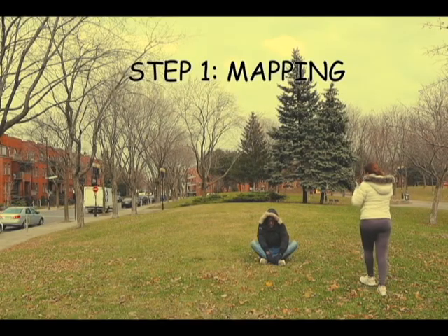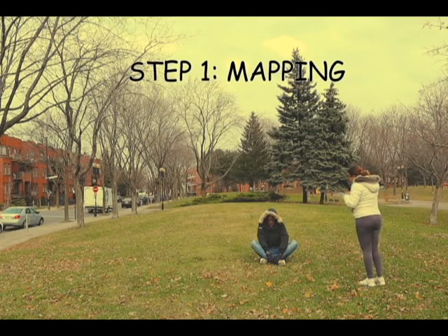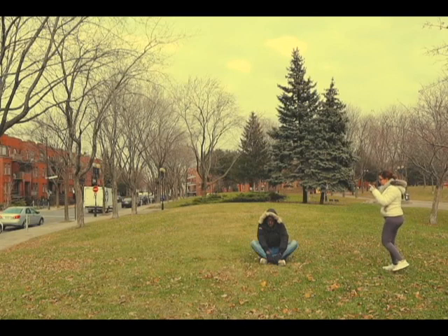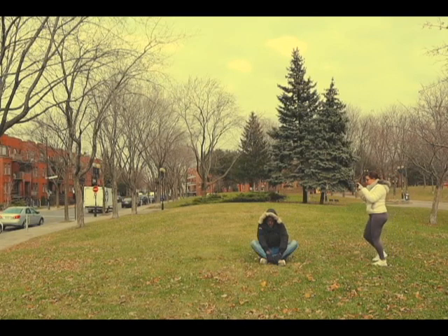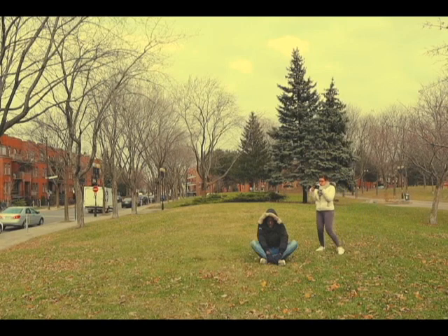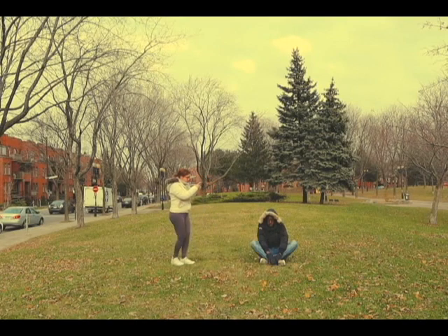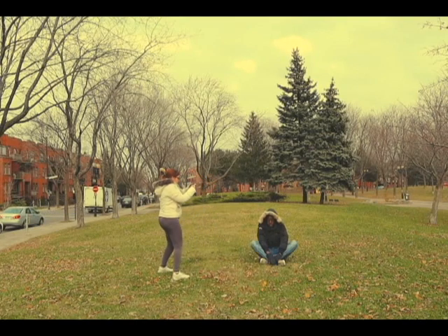Basically, the first thing when doing photogrammetry is taking pictures. This is called mapping. You have to be sure in the surrounding that there is nothing moving and use the highest resolution possible. You can use your camera, you can use your phone, just with an acceptable resolution. Each point in the scene surface should be clearly visible in at least 2 high quality images. The more, the better rule applies here.